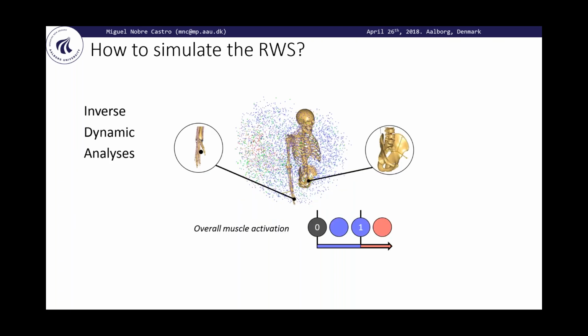So if we think of the same points that we collected previously for the kinematic protocol assessment for the reachable workspace, since those motions were performed at a very slow pace, such a way that dynamics were not influencing how people were reaching this or another point, what we did is that we discretized all of those frames, collected all the points for the 5 different tasks, and performed an inverse dynamic analysis for each one of those.